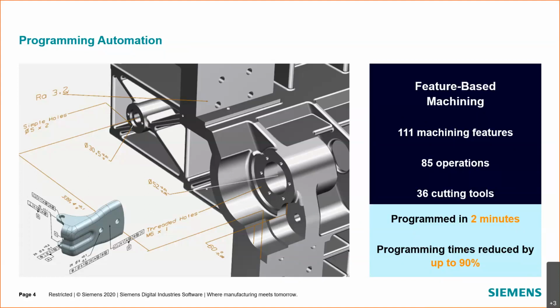We then show and explain how best to capture information, which could be surface finish, dimensional and positioning tolerances, etc., as data that will affect the selection of the machining processes and tools. So, for example, a different level of tolerance will trigger the selection of a different machining method with extra operations.